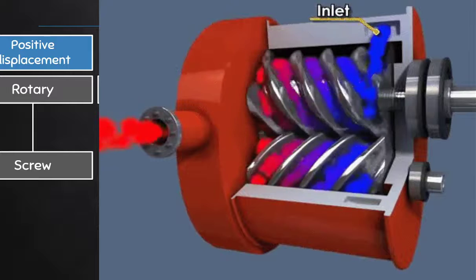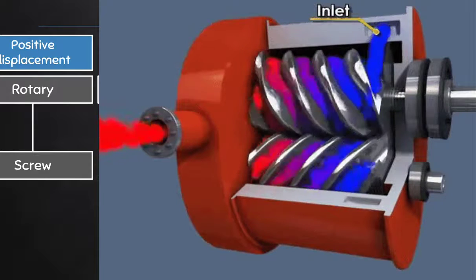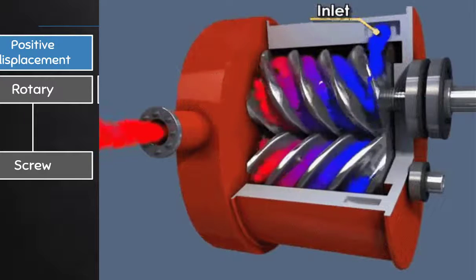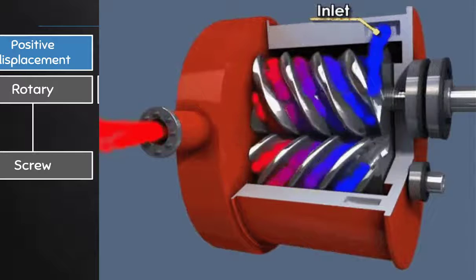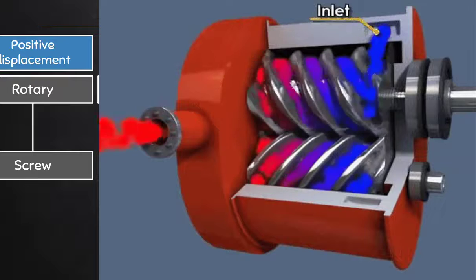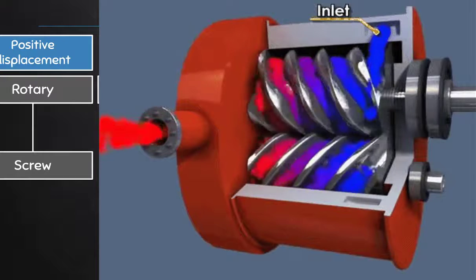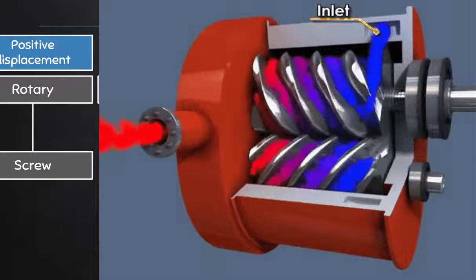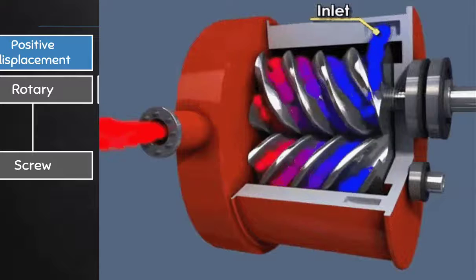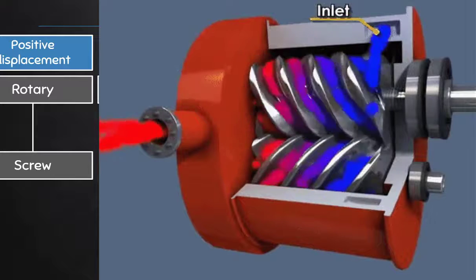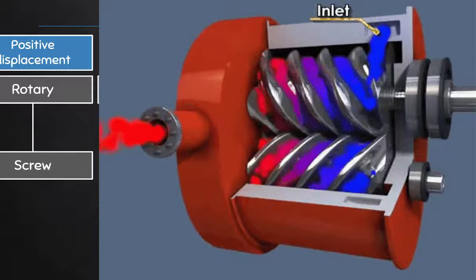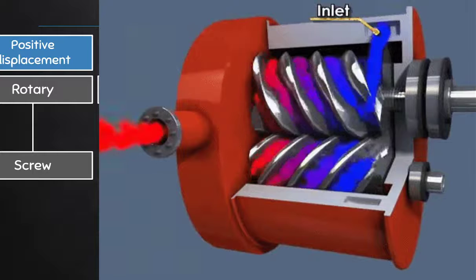And so often these screws are used to maintain the melt, to keep the melt hot due to the excessive frictional forces placed onto the polymer. Usually the polymer comes in as beads, and the kneading action heats the beads up. There are sometimes also going to be electric heaters along the sides of the screws. This is not only used for polymer melts, it can also be used in other applications as well, again for fluids that have very high viscosities.